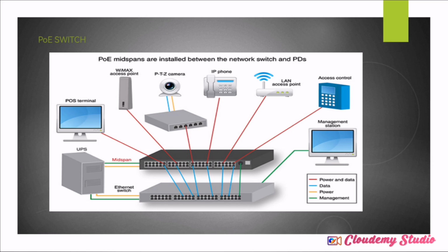What they're trying to explain is that you can use the same PoE switch for various things, not only for cameras. You can connect a laptop or a desktop, and if the ports are full, you can extend by using another PoE switch, which taps from here and splits or shares power to these other devices.